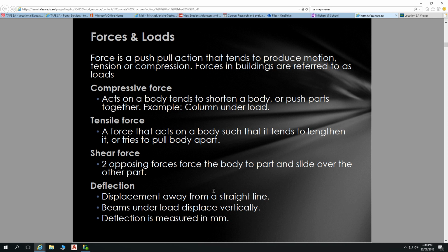We also want to ensure that we don't have deflection which causes loads on other building elements that weren't designed to have loads. A really good example of that is to look at the windows here. Certainly there's going to be some deflection in that concrete slab up above, so we have to have an area above those windows which is compressible to ensure that any deflection that happens in that slab, in millimetres, isn't going to be transferred onto those windows.